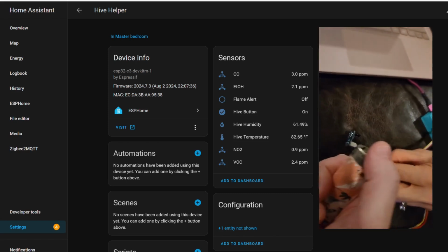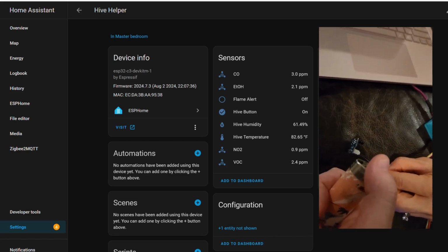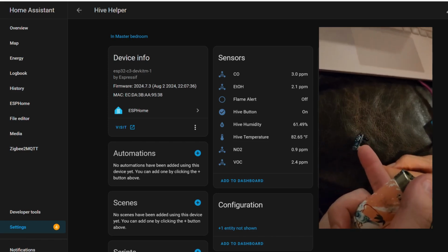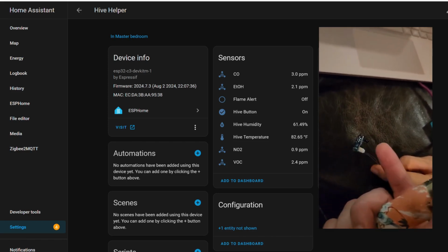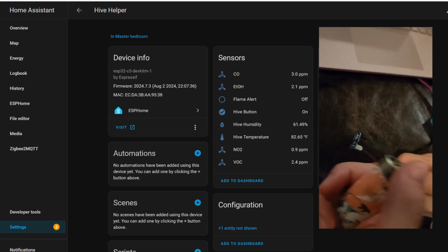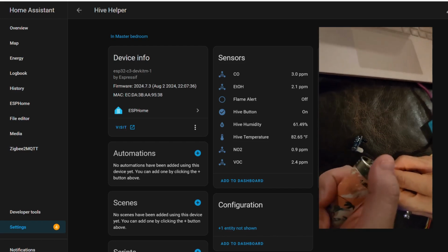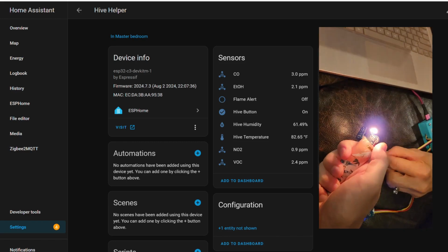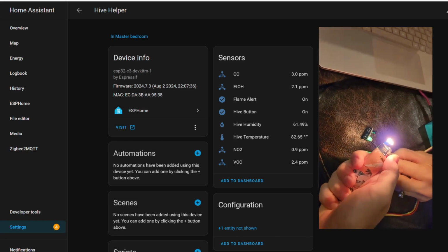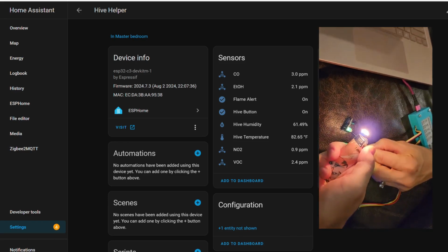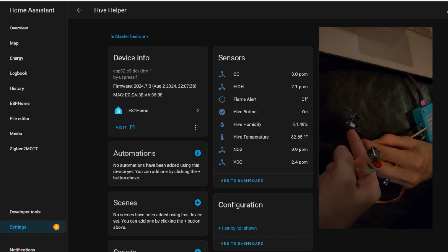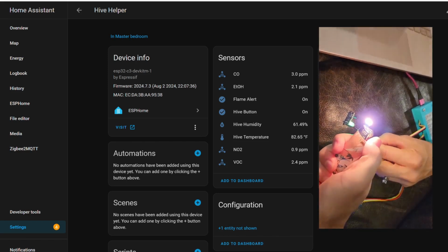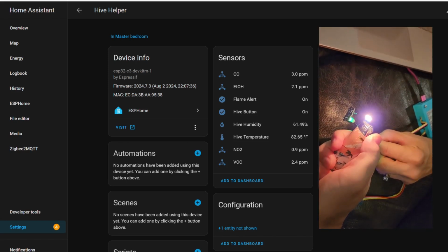Now, as you can see on the side screen here, I have a lighter and this associated Grove fire detection IR light thing. Either way, you'll see it change as soon as I light it up right about now. And as you can see, it triggers the flame when it's in front of it. And I can calibrate it further on that end. You can see the little green light appeared, which in turn shows if there's a fire.